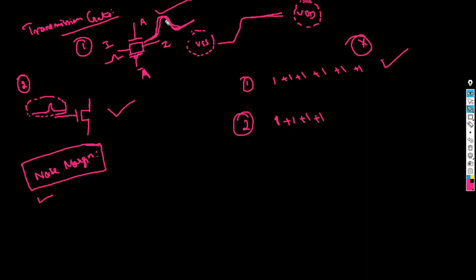But in case of this, it is likely that it might get suppressed. So from noise margin perspective, we always go with this kind of style. So when I say this, meaning you are controlling your gate. Controlling your gate is what we prefer, not the noise getting propagated to the source, and then reflecting in the drain and so on. So we won't use transmission gate just because it is having a poor noise margin. That is the main reason.